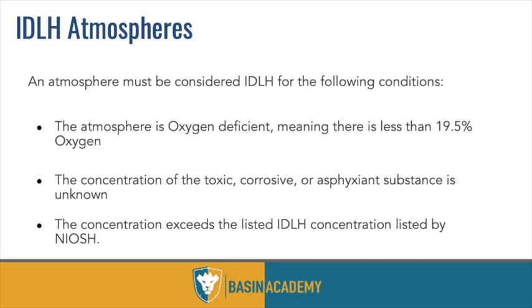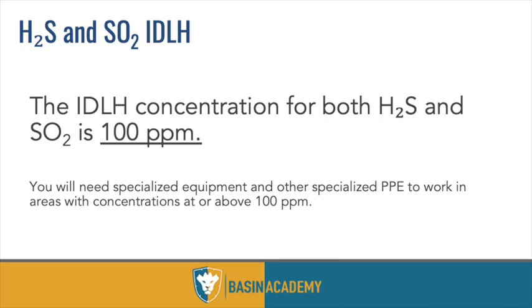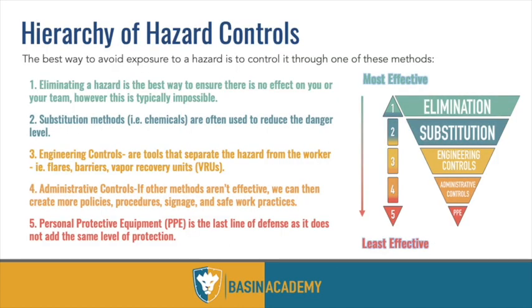So as I mentioned, there are some ways to prevent bodily harm from H2S. And this is kind of a tried and true method for any hazard, including H2S today. It's called the hierarchy of controls, where we say, okay, the best thing we can do is eliminate it completely. All right. How do we get rid of the H2S totally, right? Can we vent a tank completely? Can we chemically treat this well? Can we shut the well in, plug and abandon this thing? It's high H2S, which a lot of times they do at certain levels. That's an elimination tactic, right? Most effective, not always possible.